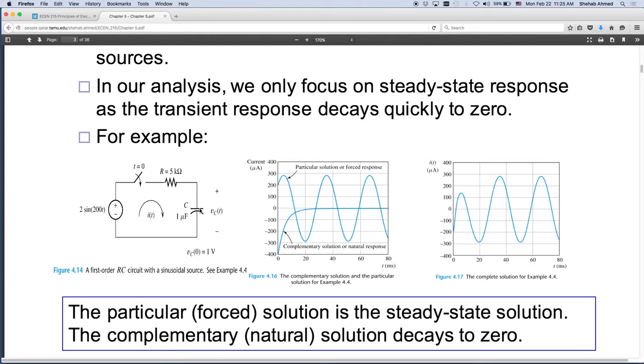What would the initial charge in the capacitor do in a circuit without the source? It would discharge through this resistor. Also, if I have a source and this capacitor is not charged, I would expect to see this source charging this capacitor if it's positive, discharging this capacitor if it's negative, right? If it's negative, I will push current in the opposite direction. So this source will have an effect on the circuit, as well as the initial charge.